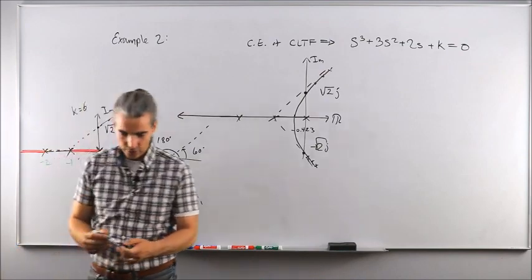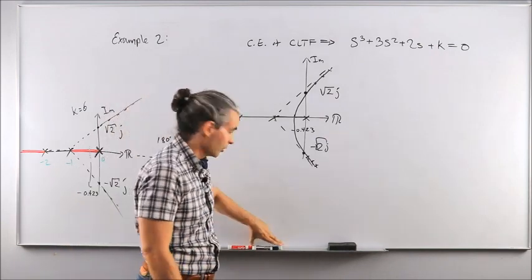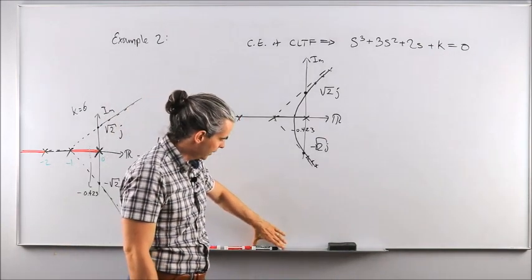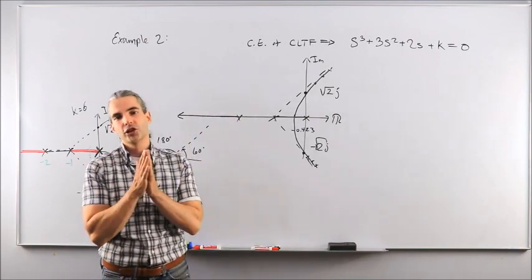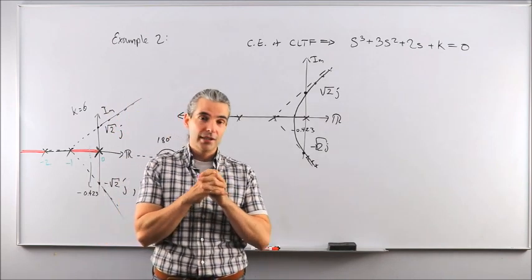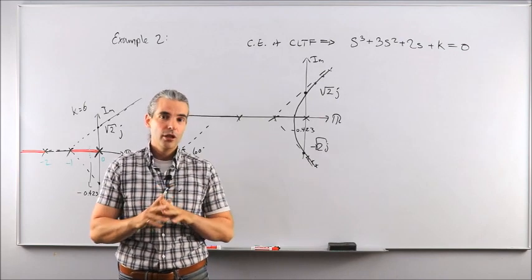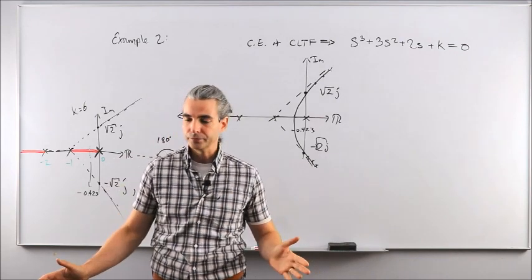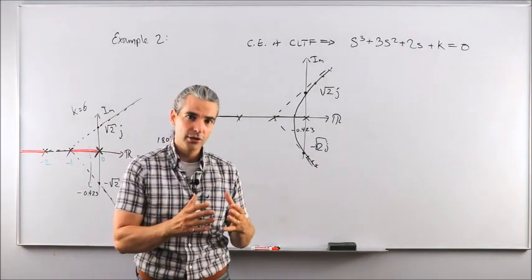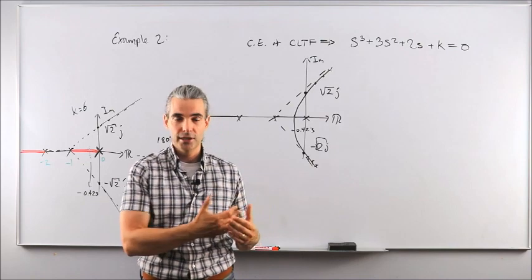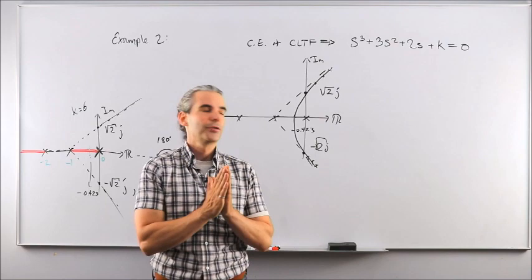It's, again, just a simple step-by-step procedure. Think of it as a recipe. You are cooking a root locus out of the main ingredient, which is your open loop transfer function, and I cannot stress that enough. If you were to begin the process with the closed loop transfer function, the whole thing would not make sense in the end. Okay, so start the root locus construction, or cooking, because this is a recipe, from the right ingredient. And that ingredient is the open loop transfer function.